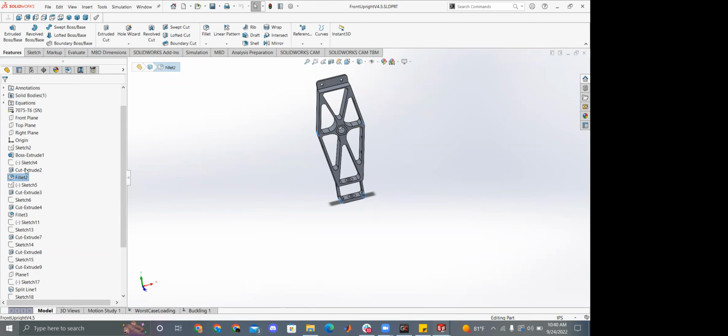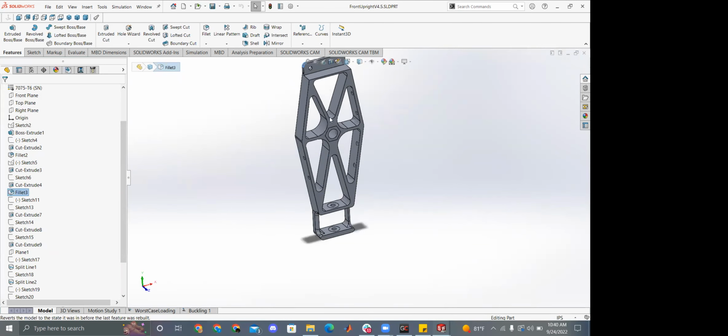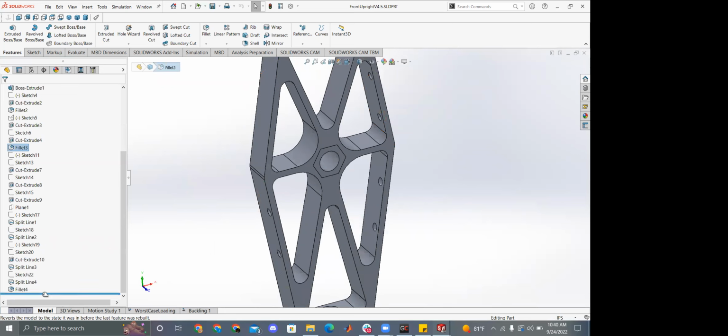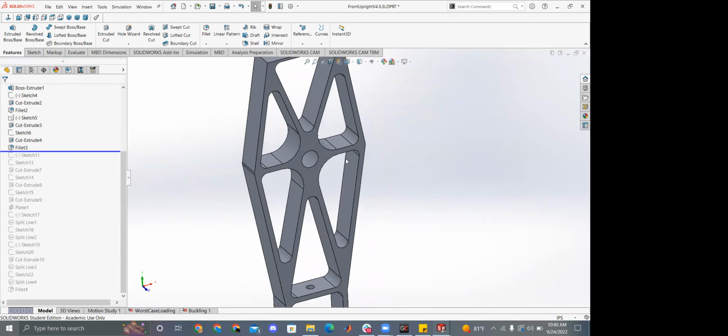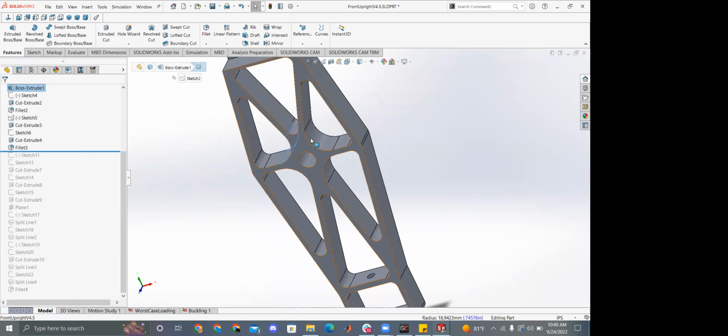And in addition, putting fillets near the beginning of the model means that they're kind of baked in. I'll talk about rolling back in a second, but if we go to this point in the part, it has these fillets built in. And fillets do mess with a lot of geometry sometimes.